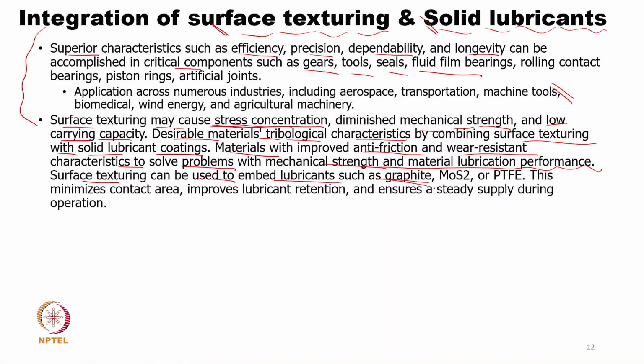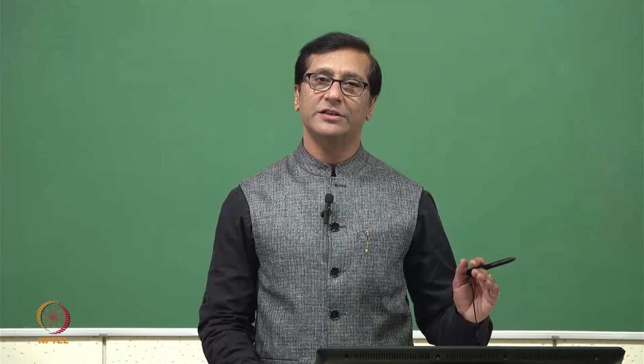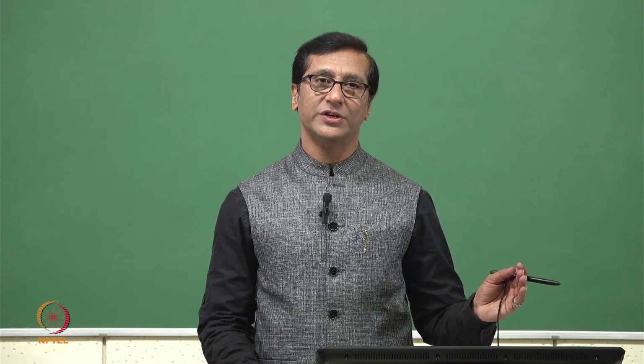Now people have tried with graphite, MoS2, PTFE. This minimizes the contact area, because if the valleys and peaks have been textured in a manner, they really give a kind of rolling action, a gliding action, and the lubricant also comes into the picture, which is not really material to material contact.